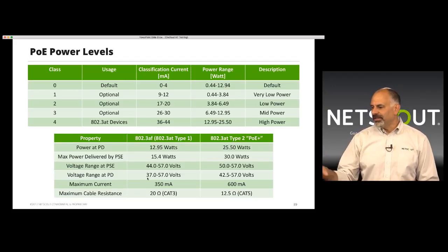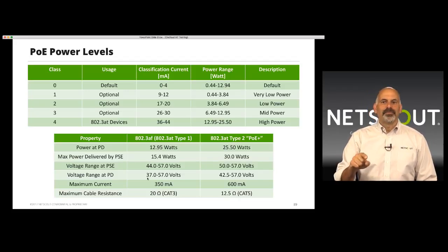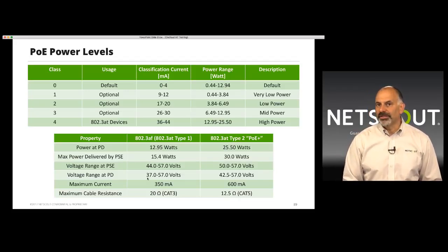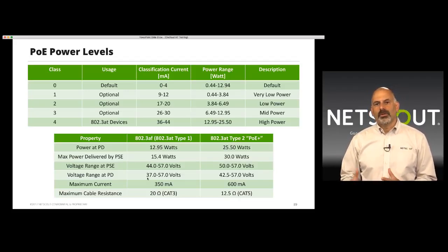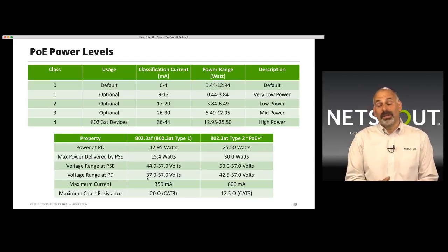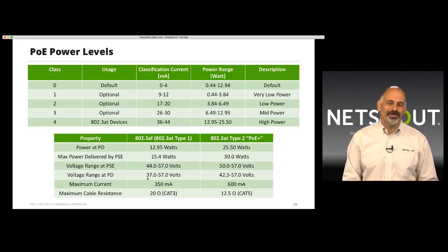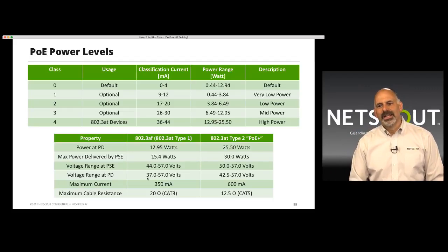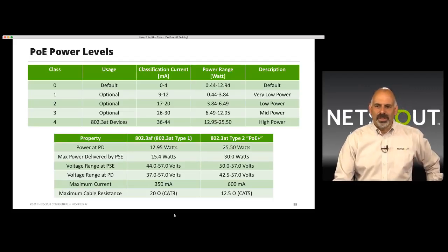What we'll find is, if we put this on a link with a bad cable, and I'll see if we can grab a bad cable here for Power over Ethernet, this will show us in that case that maybe we could only get 6 watts. That would tell us if we needed 13, we could only get 6, we fail. But maybe because we're plugging in a voice over IP phone and we only need 2.5 watts, 6 is more than enough. So this just gives us an idea of what our resistance is, etc.